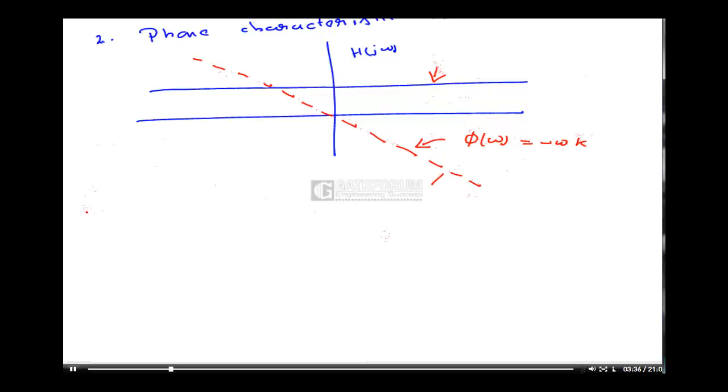Now, another one is, what is frequency response? See, generally a response to something is nothing but whenever input is that particular type of signal, what is the output? Suppose if we say impulse response, that means whenever the input to a system is impulse, then what is the output? So that is called an impulse response. Step response, whenever the input to a system is a step, then what is the output? Similarly, frequency response is whenever an input to a system is a sinusoidal function or a complex exponential, then what is the output? Okay, so we will see here important characteristics of this.